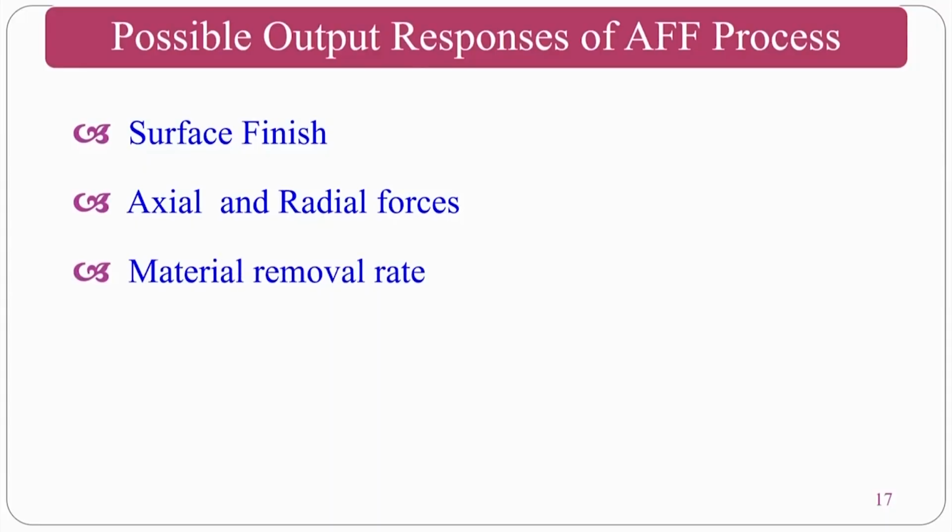Okay, material removal rate, how much material is removed. This is the least bothered, because abrasive flow finishing process is about the surface finish that you are getting, whether you have achieved the nano surface finish or not, that is the question mark as far as the current trend is concerned. But material removal rate is also one of the output parameters if at all you are going for deburring application.